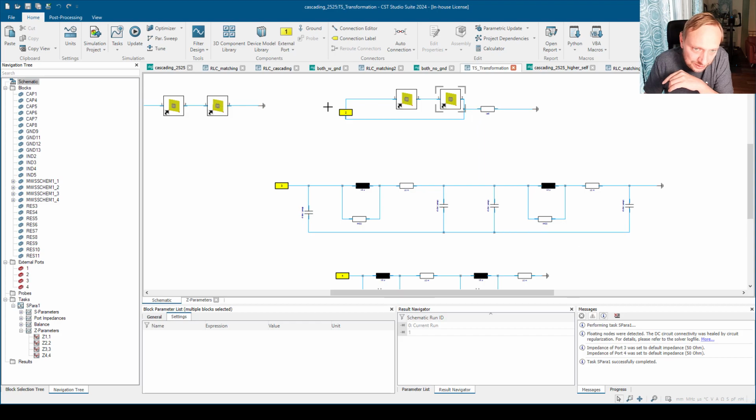The funny thing in this case, when I do a definition like this, when I have the shunt capacitances but I don't allow the current to flow to ground, I don't allow the capacitance to flow into this loop. Because in a standard setup like this, you also have a ground here, and the current can flow through these capacitances to this position. In this setup, it cannot. So you have shorted all of your capacitances, but they are not connected to ground.